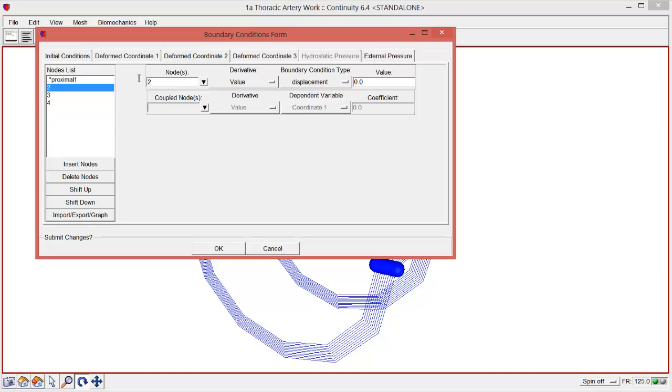Because we defined each node with these labels earlier, we can conveniently apply boundary conditions to groups of nodes, especially when refining the mesh produced almost triple the amount of nodes we normally had. Because we are holding one set of nodes fixed and closing the other, we will only apply a deformation of about 58 degrees, here in radians, to only one set of nodes.